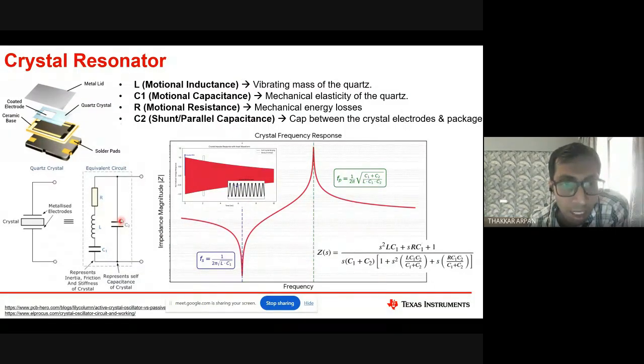So what circuit designers do is they put some kind of smart mechanism so that if the current decreases as the temperature increases, they will sense the temperature and try to pump more current, or do some smart circuit innovation, so that they will have a constant amplitude across temperature, across number of years, and all, right? So still it will have some errors, but those errors will be very small and it will be specified in your data sheet, for whatever crystal oscillator you build.